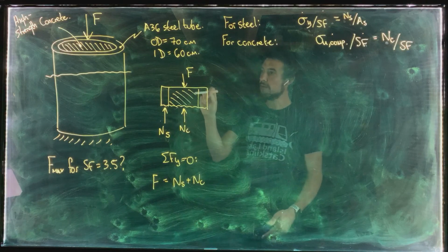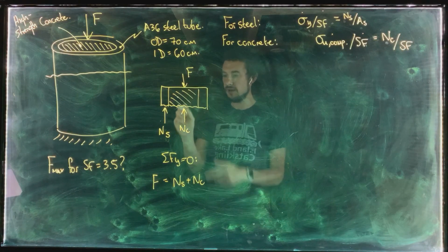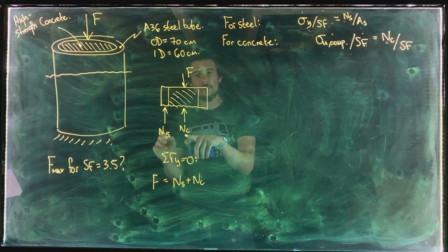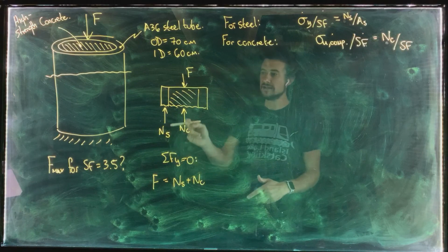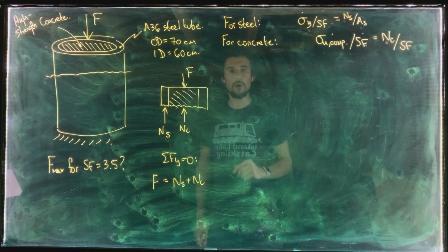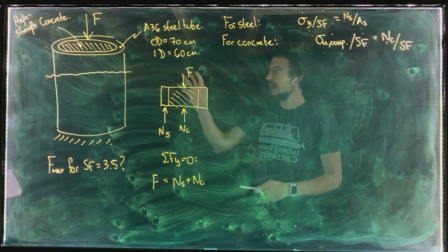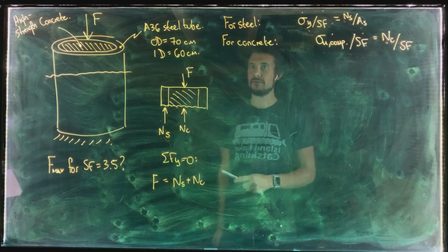So this is a problem that's called statically indeterminate because you cannot determine what the internal normal forces are from the equations of statics alone. You need a second equation to help you do that. And that second equation comes from considering how the object deforms when load F is applied, right?